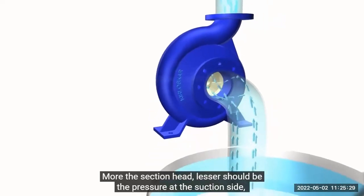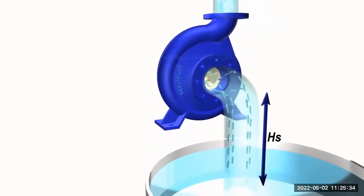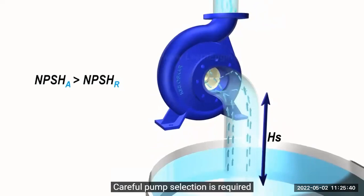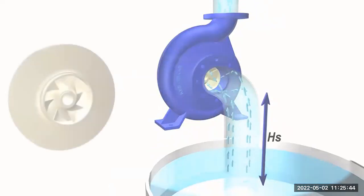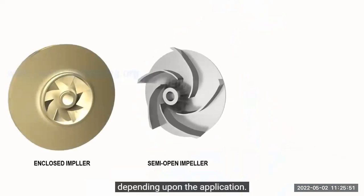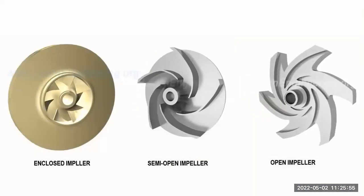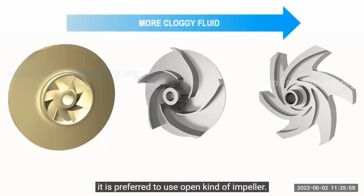More the suction head, lesser should be the pressure at suction side to lift water. This fact puts a limit to maximum suction head a pump can have. Careful pump selection is required to avoid problem of cavitation. Current impeller type is enclosed. Semi-open and open impellers are also in use depending upon application. If the working fluid is cloggy in nature, it is preferred to use open kind of impeller.